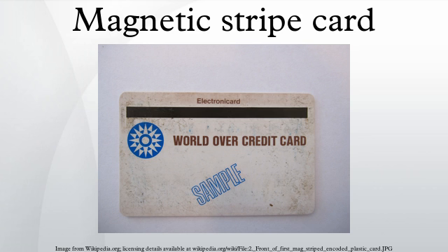Track 2 format was developed by the banking industry. This track is written with a 5-bit scheme, which allows for 16 possible characters: the numbers 0 to 9, plus the 6 characters : ; < = > ?. The selection of 6 punctuation symbols may seem odd, but in fact the 16 codes simply map to the ASCII range 0x30 through 0x3f, which defines 10 digit characters plus those 6 symbols.